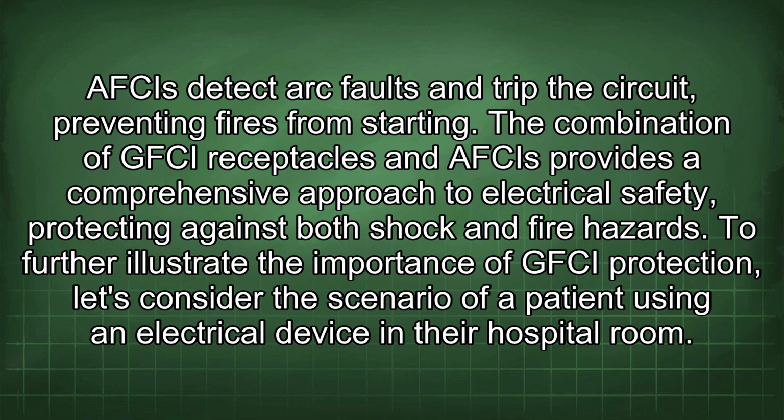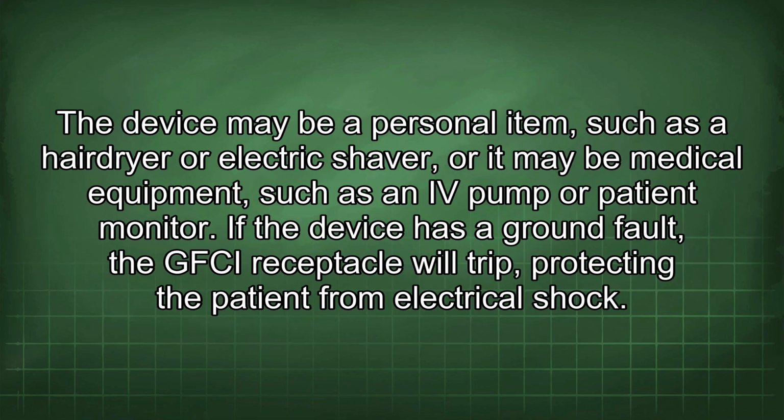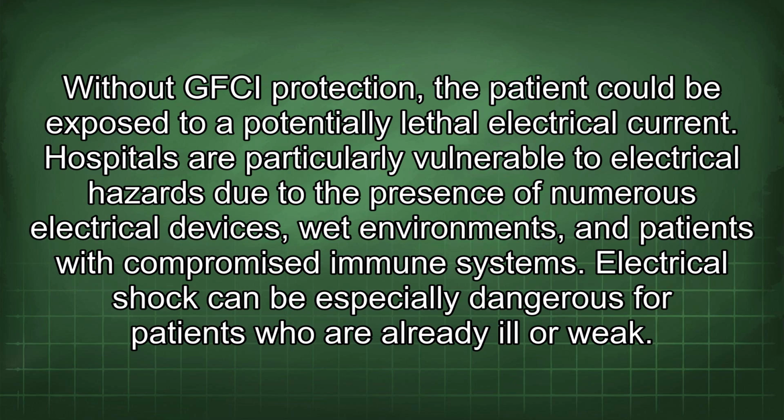To further illustrate the importance of GFCI protection, let's consider the scenario of a patient using an electrical device in their hospital room. The device may be a personal item, such as a hairdryer or electric shaver, or it may be medical equipment, such as an IV pump or patient monitor. If the device has a ground fault, the GFCI receptacle will trip, protecting the patient from electrical shock. Without GFCI protection, the patient could be exposed to a potentially lethal electrical current.